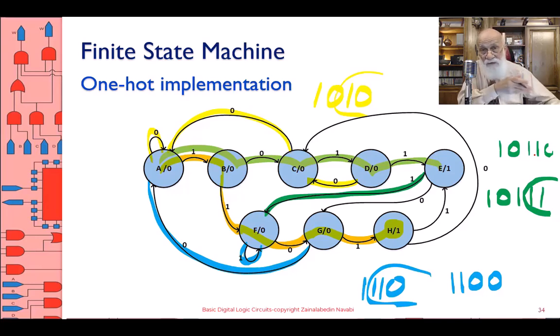Okay, then again start looking from the right hand side, see what's the most number of bits that you can reuse, and therefore you only see a 1 0. It doesn't matter for which sequence it is. Okay, it is a 1 0, and then state, I'm sorry, a 1 1 0, a 1 1 0, which is pretty good. Okay, and therefore a 0 in the state E takes you to a state where a 1 1 0 has been saved, which is state G.